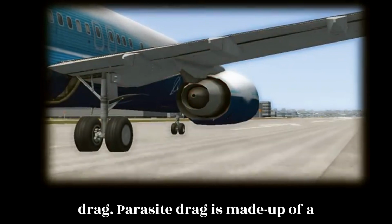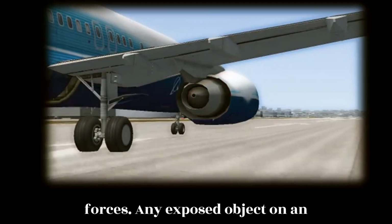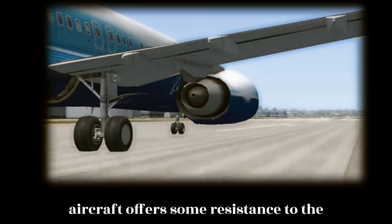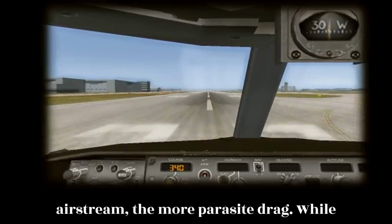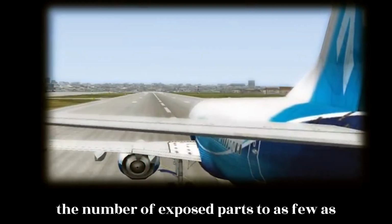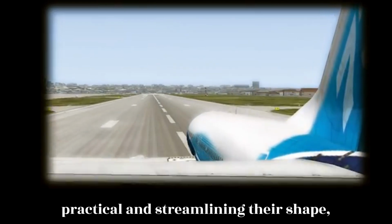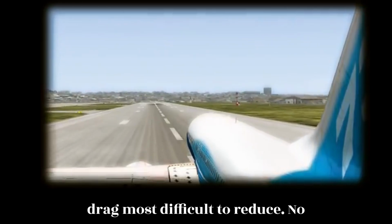Parasite drag is made up of a combination of many different drag forces. Any exposed object on an aircraft offers some resistance to the air, and the more objects in the airstream, the more parasite drag. While parasite drag can be reduced by reducing the number of exposed parts to as few as practical and streamlining their shape, skin friction is the type of parasite drag most difficult to reduce.